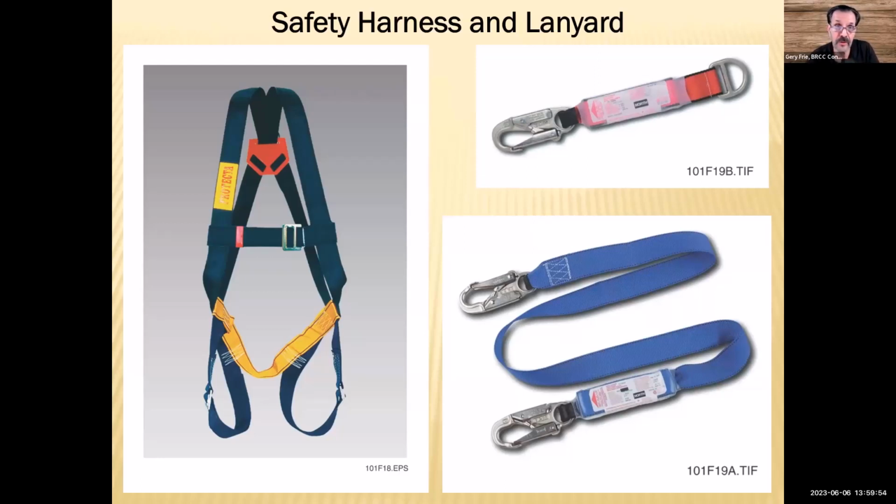The other thing you see in these 2 pictures of the lanyards is that they've stitched up a bundling of that webbing. That synthetic strap is stitched together into a bundle there at one end on purpose, so that as you fall, it'll decelerate you. It'll slow you down, arrest your fall by unstitching itself, which means then when that stitching has come loose, you've got to take it out of service. That one has been spent.